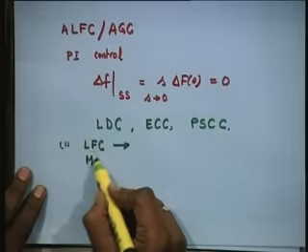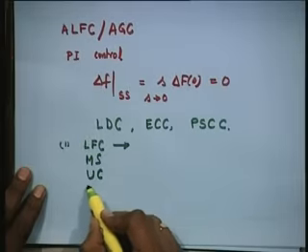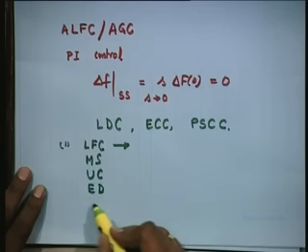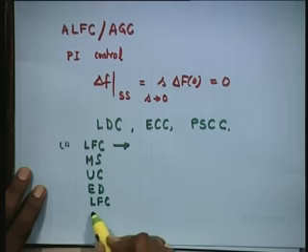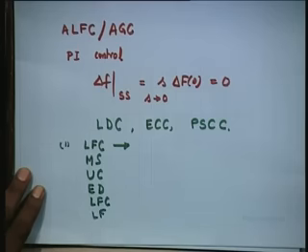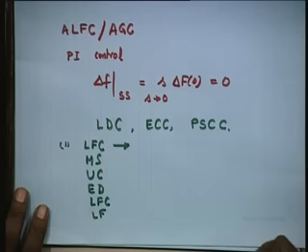What will be the load at 11:30 today? Now it is 11:26, not a.m., not p.m. 11:30 a.m., I am interested. That is very short term. So I have to run maintenance scheduling program, unit commitment program, economic dispatch program, and LFC, load flow. All these various functions are being solved all the time by engineers sitting in the load dispatch center.